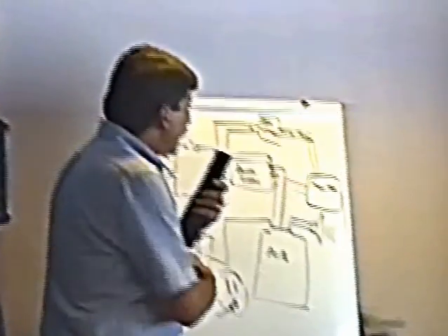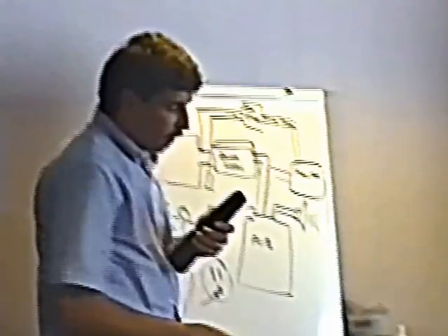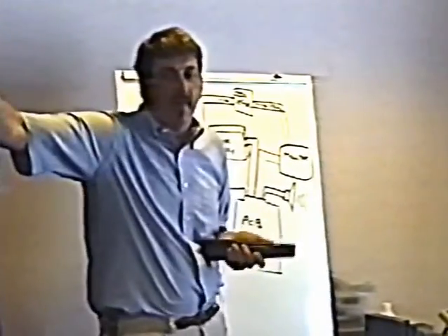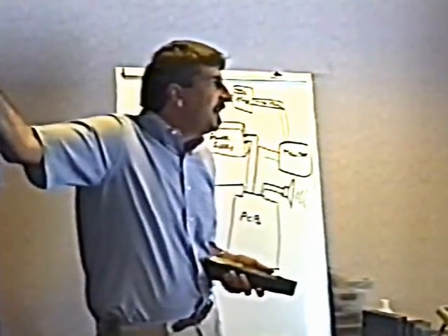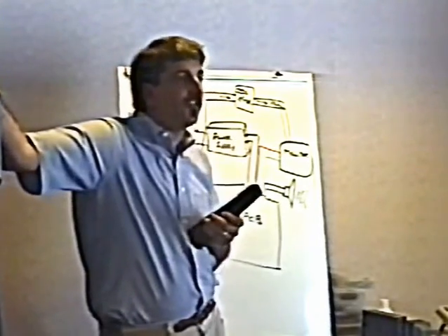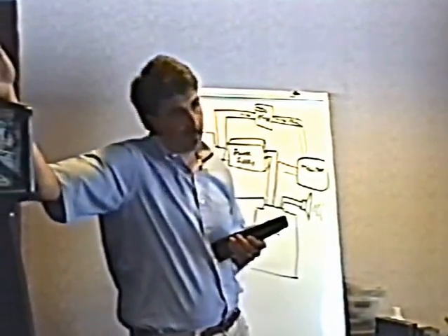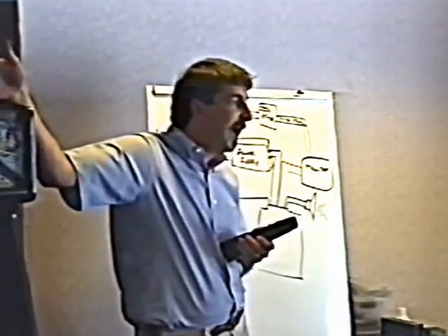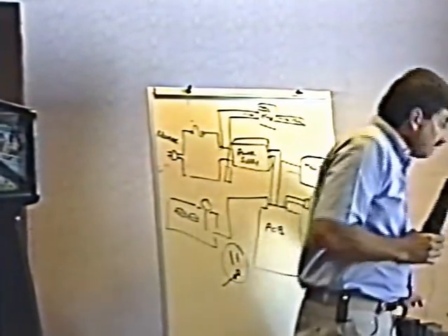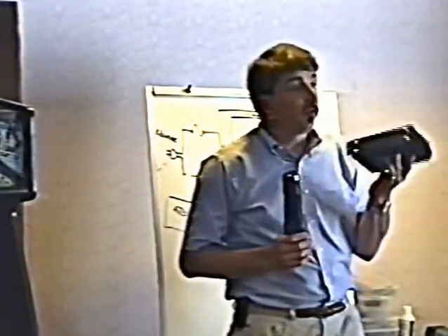Make sense? Now, one common problem that we have a lot is the 5-volt power supply just goes out of adjustment. After a period of months or years with temperature changes and changes in component values, the output voltage of the power supply may drop. It probably will drop.